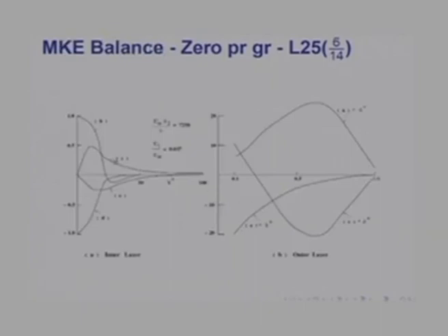That is what you see here, that C, the turbulent diffusion term, is positive in the range 0 to y plus up to 100, whereas the term E, the loss of energy to turbulent kinetic energy production, is negative.